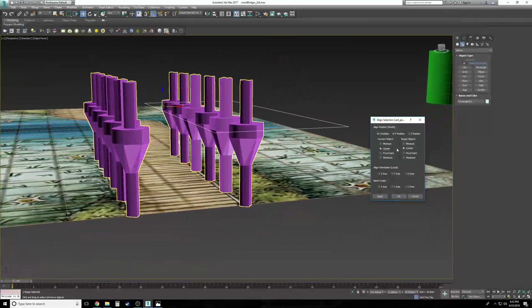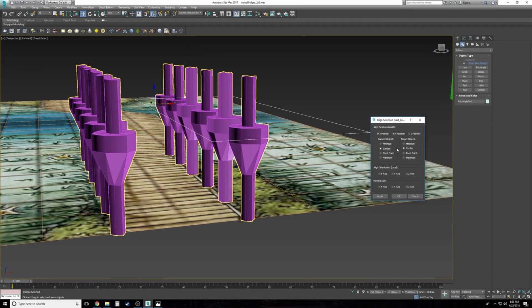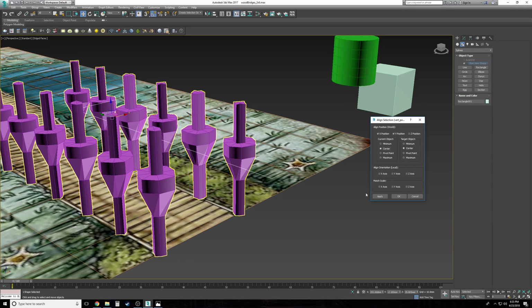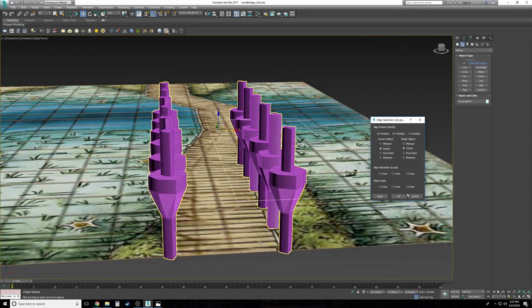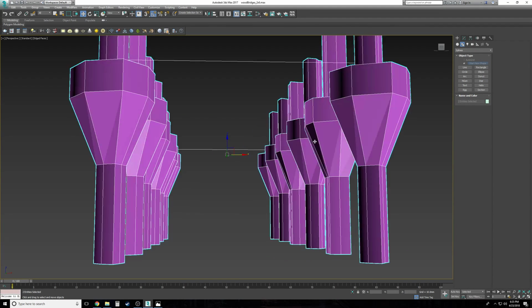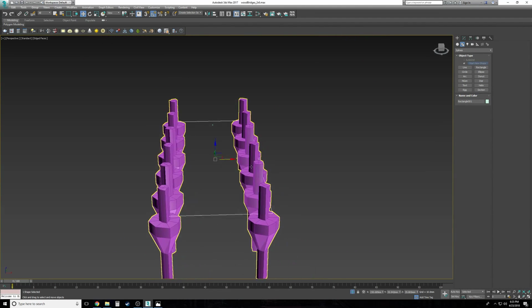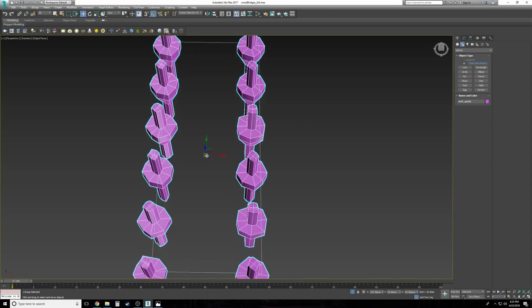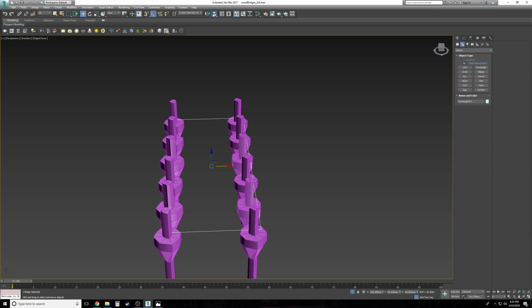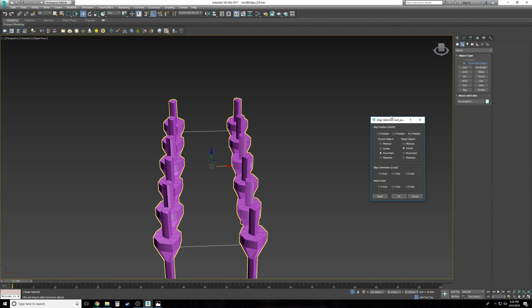And that did exactly what it's not supposed to do, ladies and gentlemen. You see what it did? It basically aligned to one of these individual posts instead of the whole enchilada like it's supposed to. That's not very nice. I'm going to isolate this and double click that. I've got it centered right there. See how that anchor point's right there? This thing should anchor to the actual object.